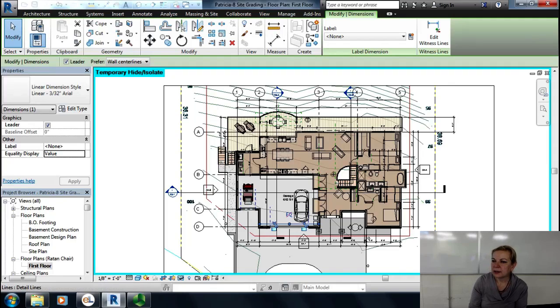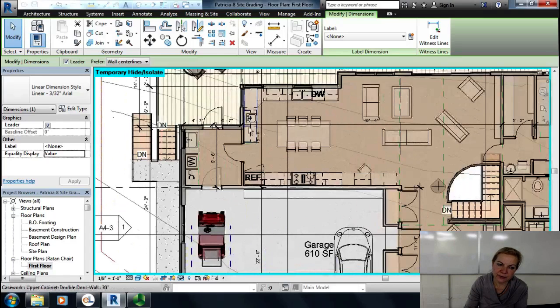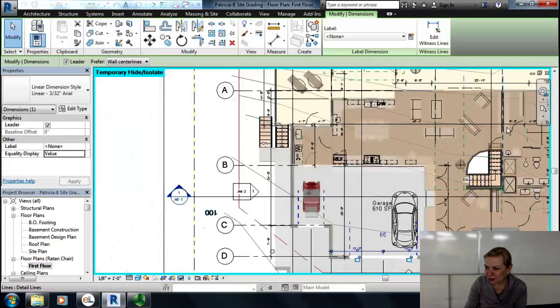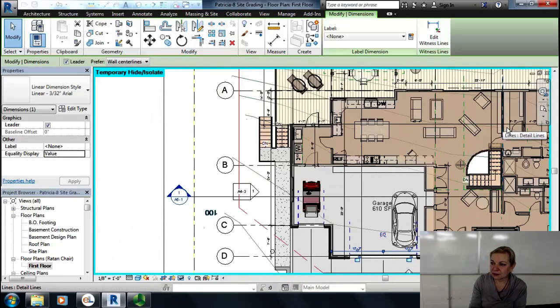So you need to know, I know that this is drafting 1 and 2 and your CAD classes, but in case you don't know, I require you to do the proper strings of dimensions. In other words, interior dimensions show strings, continuous strings of walls, and I would suggest you go to center lines. Otherwise, you're going to dimension those 4.5 inches, and they're just going to look very, very messy. I would say on the interior, you can go from the interior face, but then when you get to your typical 4.5 inch partition, dimension everything to center line, which is something the carpenters love anyway.